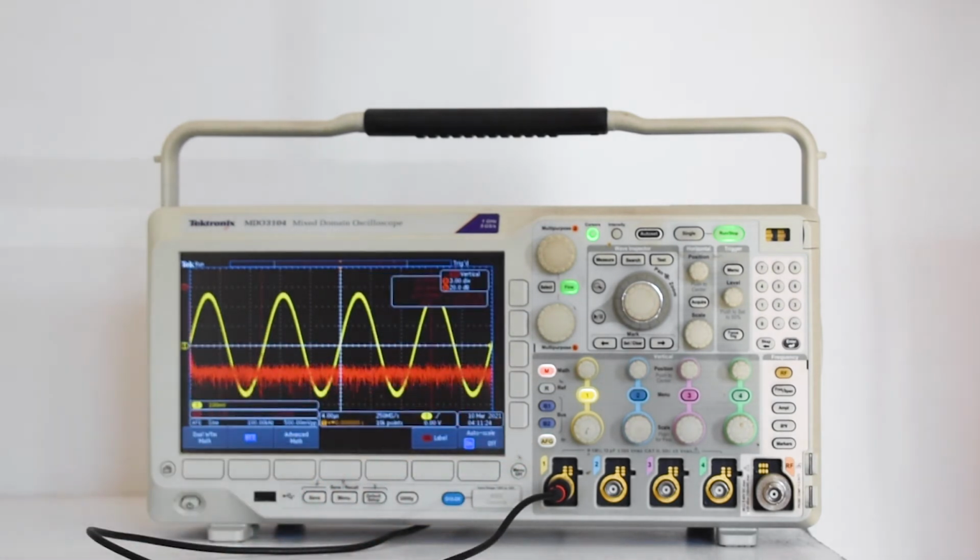Now the frequency domain is shown in the same screen along with the time domain, which is what a mixed domain oscilloscope does, and this is very useful in some troubleshooting operations. In the frequency domain, again, we see amplitude plotted against the vertical y-axis, but it is now in units of power rather than volts, and the scale is logarithmic for viewability rather than linear.